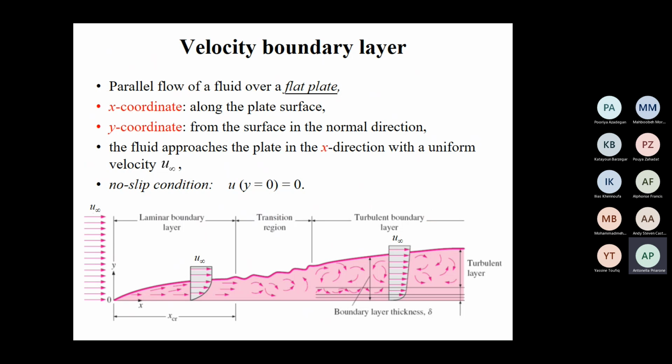At the beginning, I have laminar flow, that is ordered flow without eddies, and I have a developing of this type of profile. Then I have a transition zone in which the Reynolds number increases, and I have the change between the laminar regime and the turbulent one. The turbulent one is characterized by eddies. Eddies means in Italian vortici.